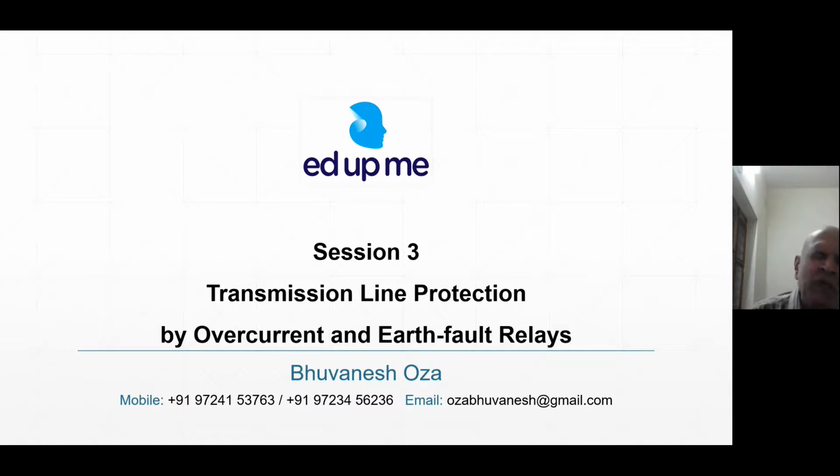To solve that problem, we started with current discrimination, because we know that as we go away from the source, the impedance goes on increasing, and as current is equal to E upon Z, Z increasing means current will decrease. Therefore, current can be used as a discriminating quantity. But then we saw that there are about 6 to 7 problems, and therefore instantaneous overcurrent relay alone cannot be used. No doubt, it can be used as an ancillary, auxiliary, assisting feature. That we will keep on seeing in the slides to come.